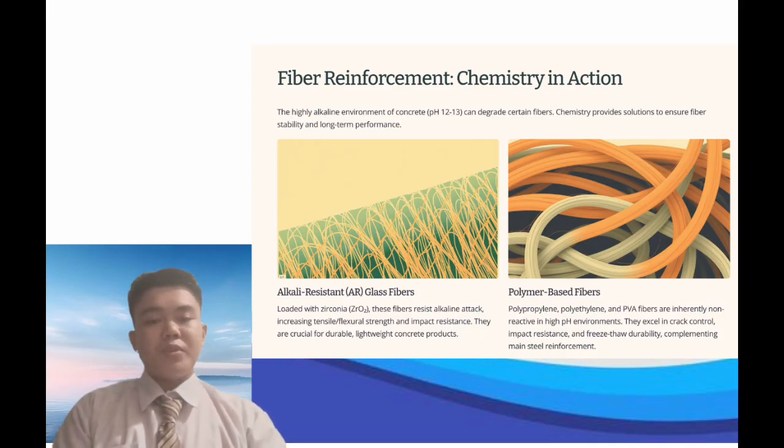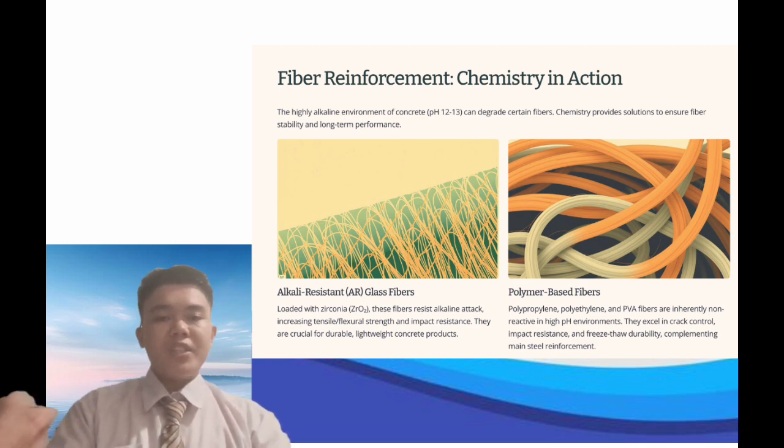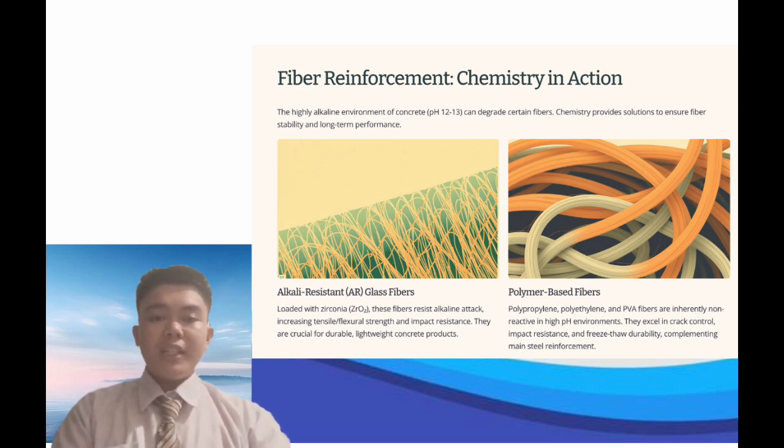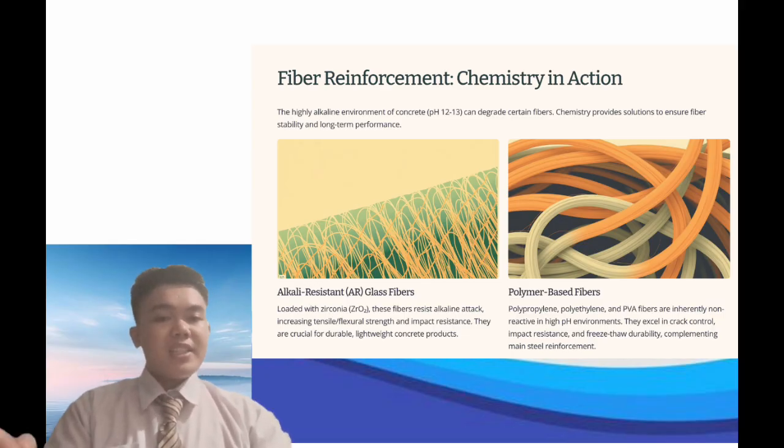These fibers improve cohesiveness, reduce segregation, and increase fire resistance. But they do not replace main structural steel. Instead, they complement its performance and offer value in specific applications.